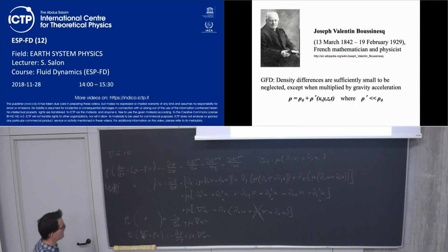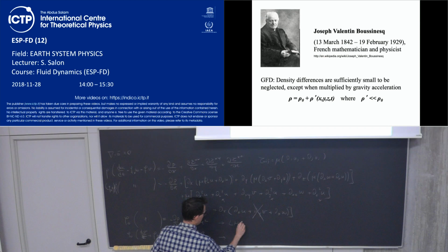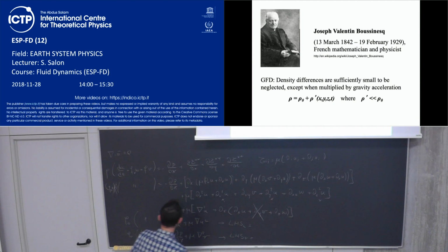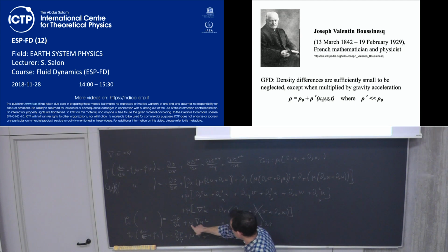We can do a little bit more, and we can divide everything by rho 0. So simply what we have here will be only the part related to the left-hand side of U, left-hand side of V, and then we will have just minus 1 over rho 0 dxp, and here when we have mu over rho 0, we have the kinematic viscosity nu.